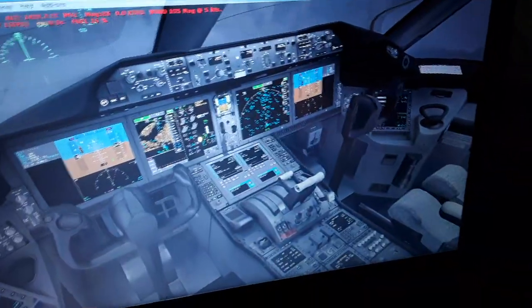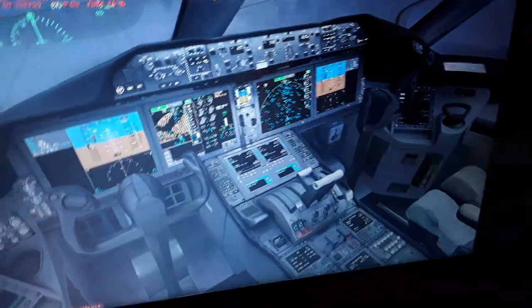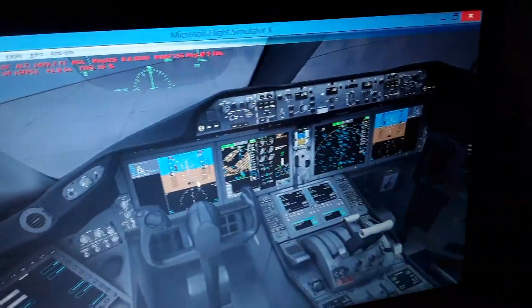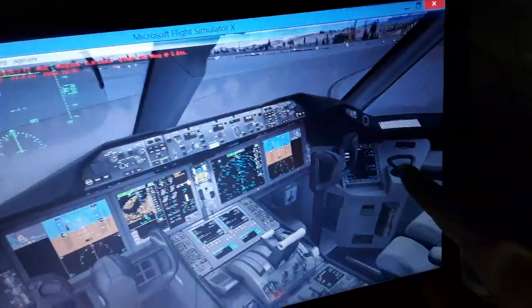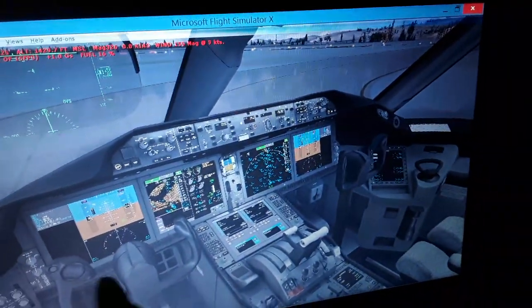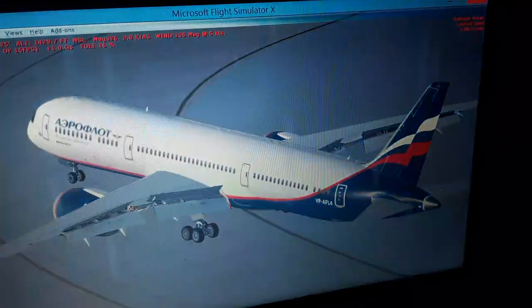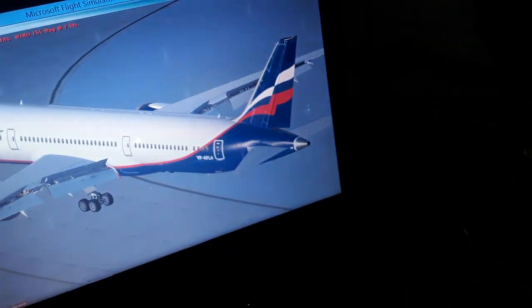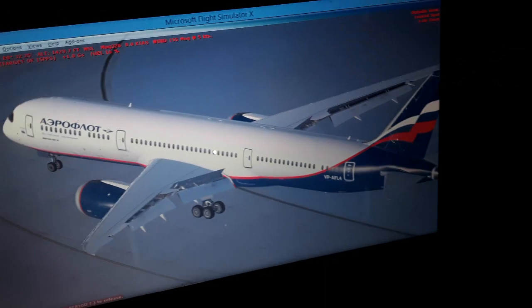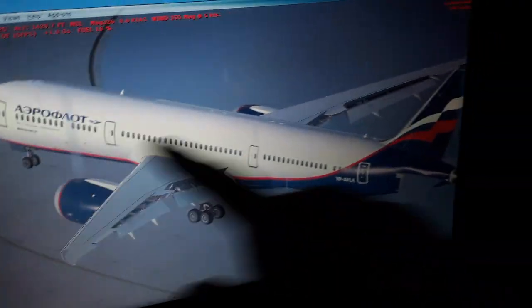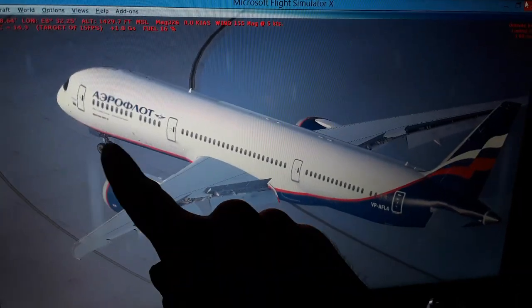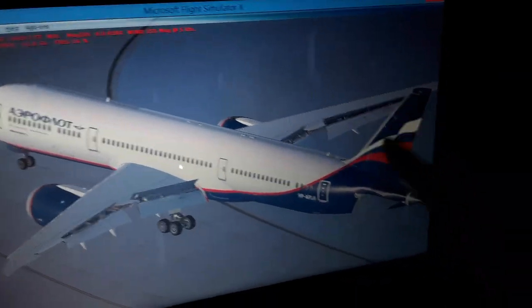So you can see both sides are interconnected, move together, and also for the nose wheel steering, and we have the tiller for the nose wheel steering here and here. You also have the toe brakes, you can press the top surface of the rudder pedals, and you brake. So we have the rudder used for directional control, also simultaneously with the nose wheel when we take off from 0 knots up to 45 knots, like 72 kilometers an hour.